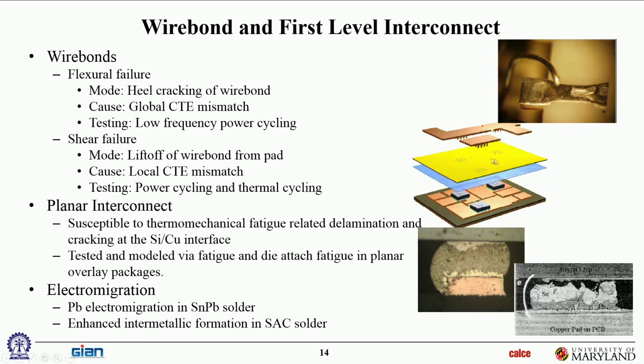No. GE makes a planar module, which they actually call power overlay, POL. They market it as the POL design. And we actually did some studies on that. And there the challenges are the vias will fatigue because you're talking about extremely severe temperature cycles. The vias, either the via barrel will fatigue or the via will pull away from the die and so on. So planar packs have that interface between the silicon and copper where you make the via connections, which is sometimes a challenge.